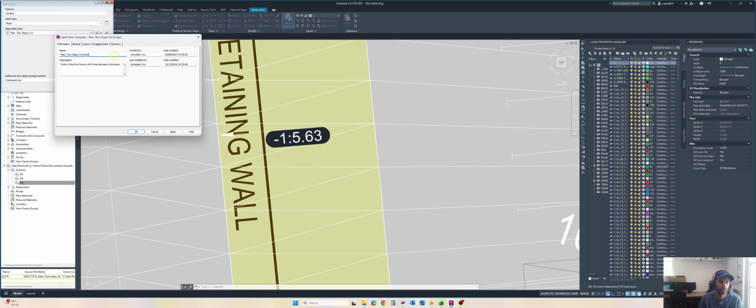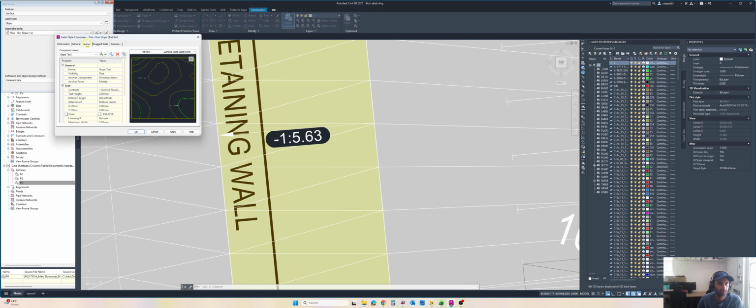I can say red. So in the layout, you can change the height of the text, but I'm fine with this one at 1 to 200 scale. But if you use a different scale, you can change the heights from here, and you can change all of these settings as you want. If you want to change the arrow, you go to component and direction arrow, and you can change the arrowhead and the minimum length from this component.